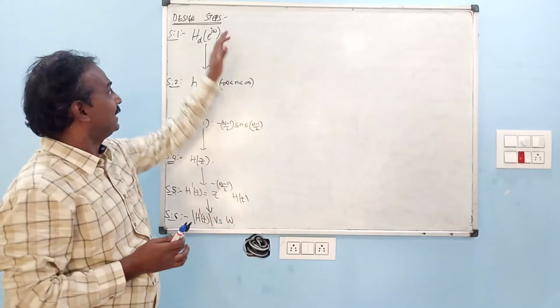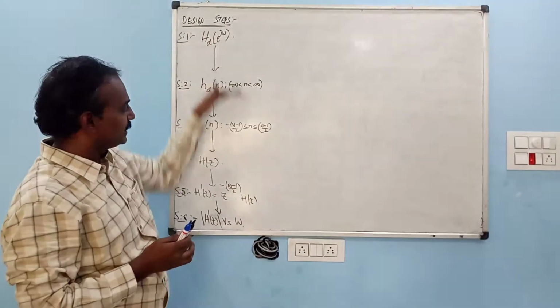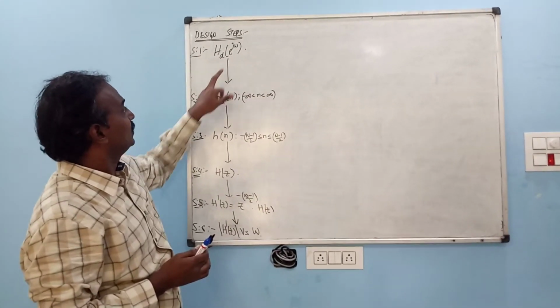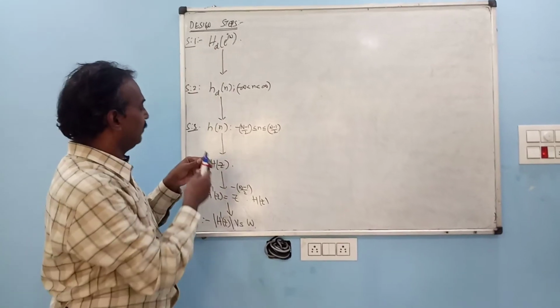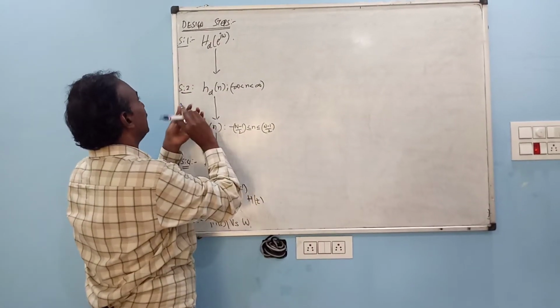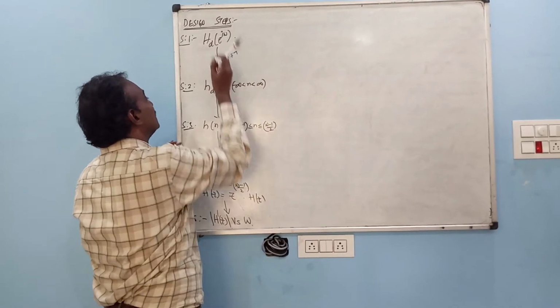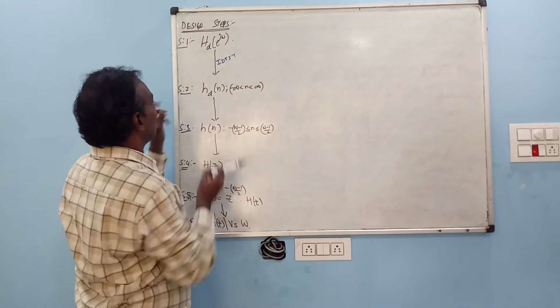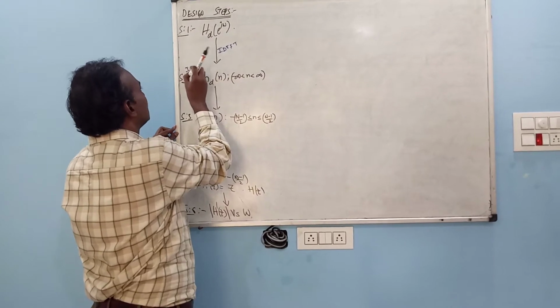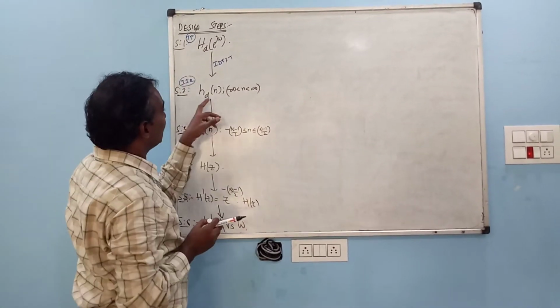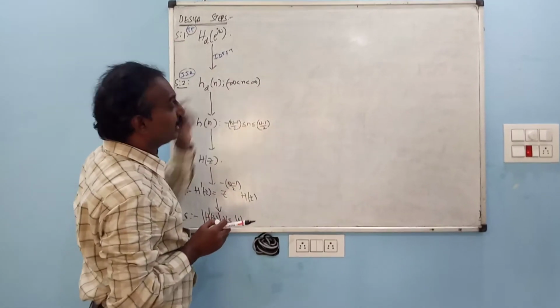Let us see graphically the steps we have seen now. First step is the given transfer function, the desired transfer function. From that we applied the IDFT, inverse discrete time Fourier transform, to get the infinite impulse response. This is the transfer function given, and once I get this impulse response, it is in the infinite range.